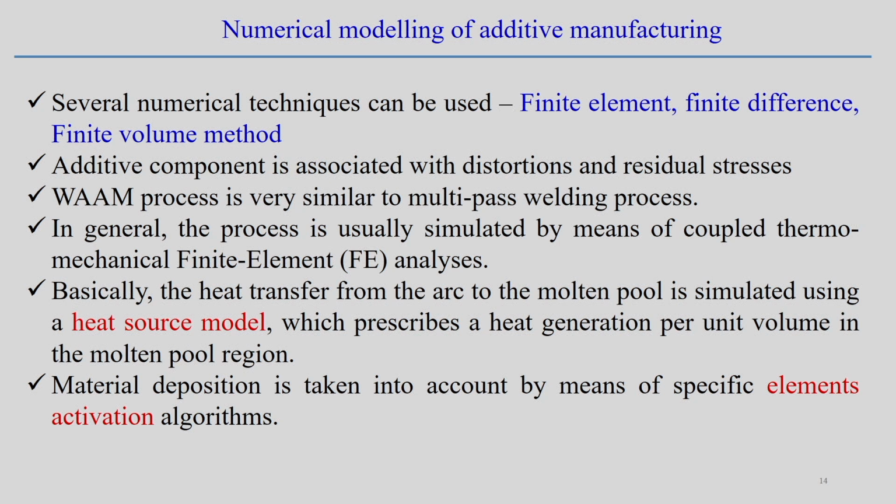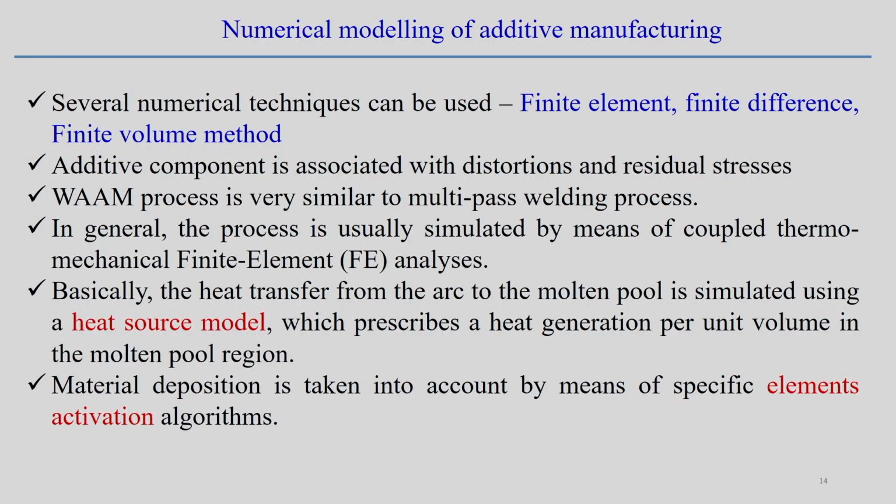So, sometimes we work on how we can manage the residual stress in an additive manufacturing component. Now, when you look into the heat transfer, the interaction between the heat source and the substrate material can be represented in the form of a heat source, and in most cases we define a volumetric heat source. That heat input can be utilized through the governing equation. I will show how it can be done.